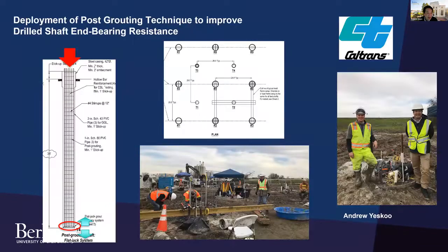Here's another work that we did. In this particular case, it's what we call a post-grouting technique to improve the base resistance or base stiffness. And I'm not going to show you the details of what we did, but while we do post-grouting, we can see how the strains are developing underneath. But let's say we finish that, and then you apply a load from the top to see how the strain is distributed inside this particular pile.